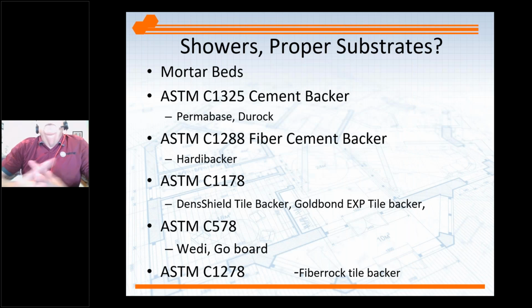Also, we've seen in a lot of multifamily homes, showers, senior living facilities, improper substrates. We see the gypsum board just run into the shower, and they say, well, you're going to waterproof it anyways. What's it matter what board? TCNA has some very direct requirements on what's supposed to be used along with the building codes. And these are your proper substrates for showers, and the details that go along with them are in TCNA, but just make sure that the shower has a different backer board than what's on the rooms outside the shower itself.